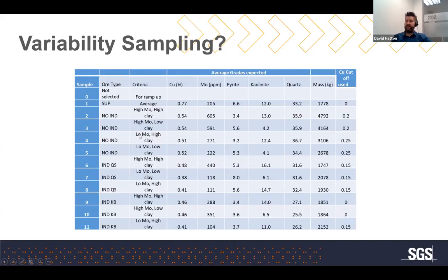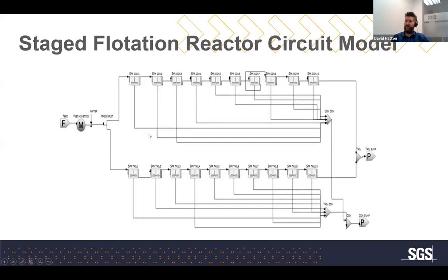From the samples that were available, it was a large amount of drill core. We were able to run our flotation simulator on the copper circuit, and we were able to calculate how much concentrate we expected from each of the different composites that we'd put together. And so we could determine whether we had enough material to collect the further downstream material for sampling and testing.